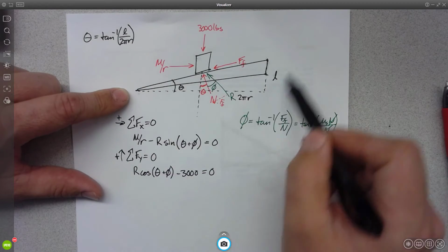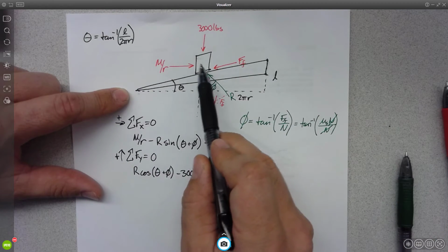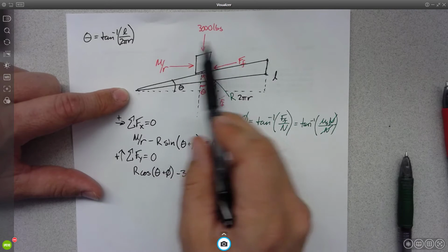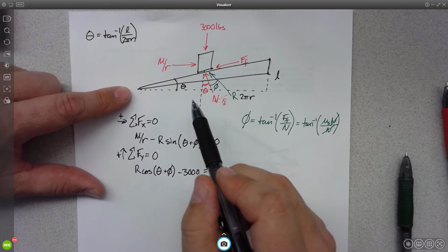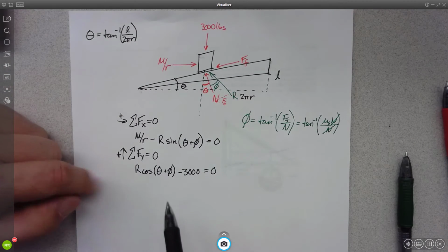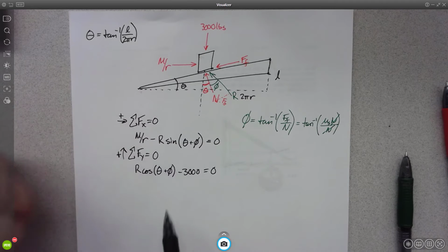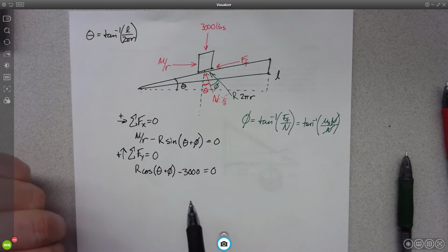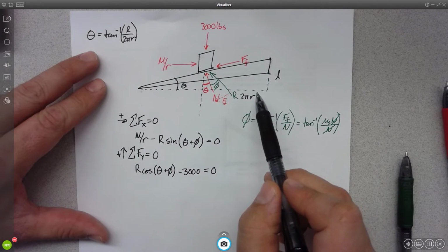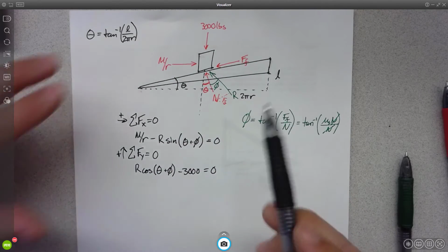And you can draw this problem as a simple inclined plane. And so that makes it much easier. So if you forget, say on a final, what the equation is for the torque required to move a screw, that's not a problem for you because you're a good student, and you can just go ahead and draw the wedge and solve it.